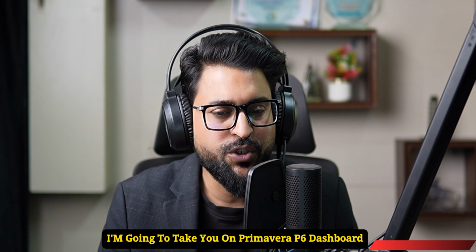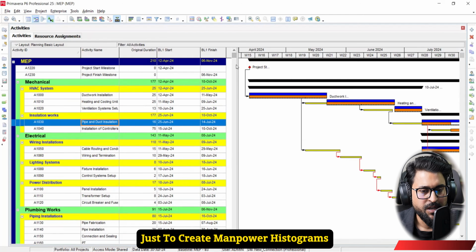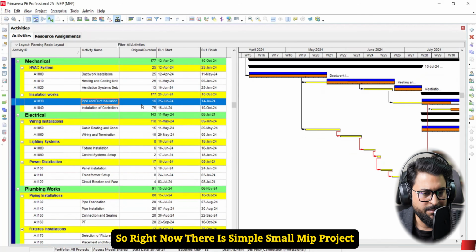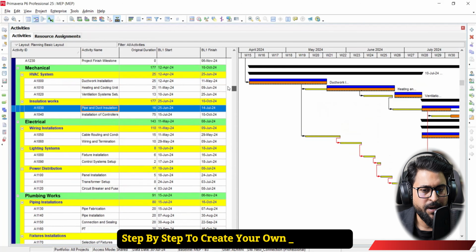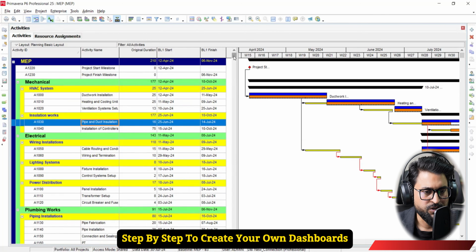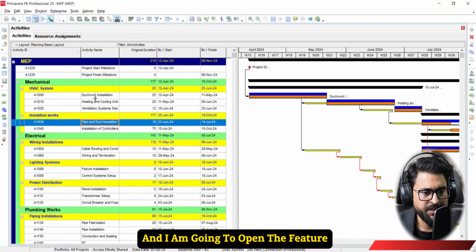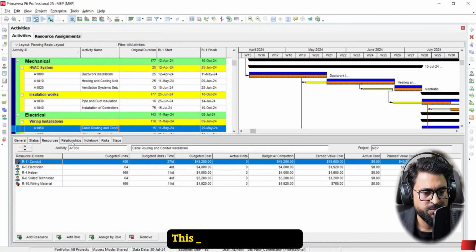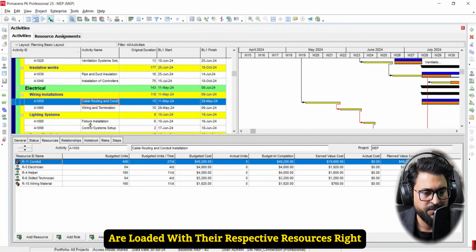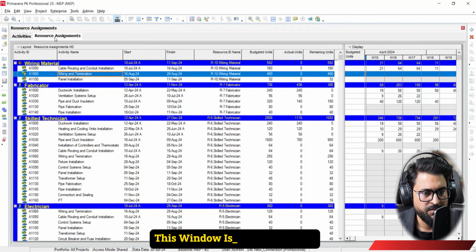Right now I'm going to take you to the Primavera P6 dashboard to create manpower histograms. There is a simple small MEP project and I'm going to use this data and teach you step by step to create your own dashboards. So we have this MEP project, and I'm going to open it, and this is resource loaded. If I click over here in the activity details, all activities are loaded with their respective resources. And when I take you to resource assignment, this window is already open.